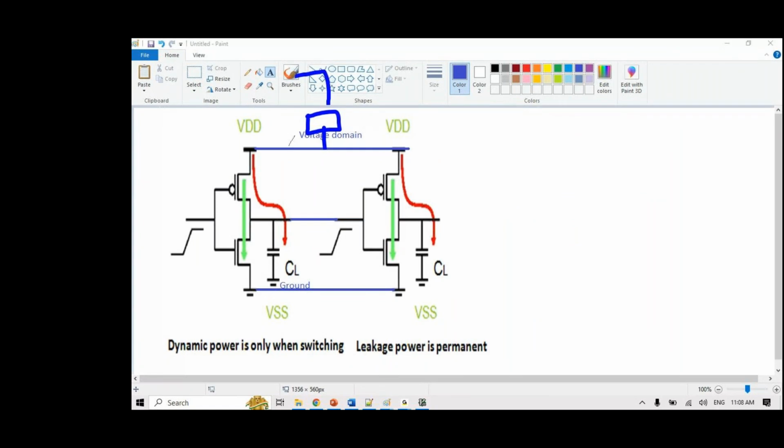Here the main powers will come from the PMIC. I mean, the same VDDs, right? There will be so many VDDs. See, at the end of the day, there will be one point from where, assume this is VDD, this is PMIC, from where let's say 1.2 volt power is coming. You'll use the power switch here, and to this entire thing you'll connect.